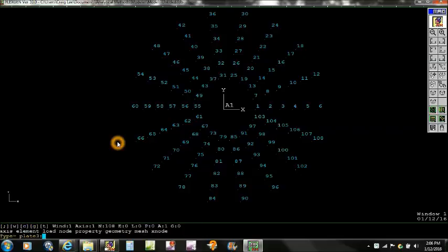Now we need to insert the elements. We're going to use plate 3s, which are triangles, and we have to create some properties. Element property 1 here, we'll create that. Now we're going to go with the standard material, standard material number 85, which is copper tube, or just copper.